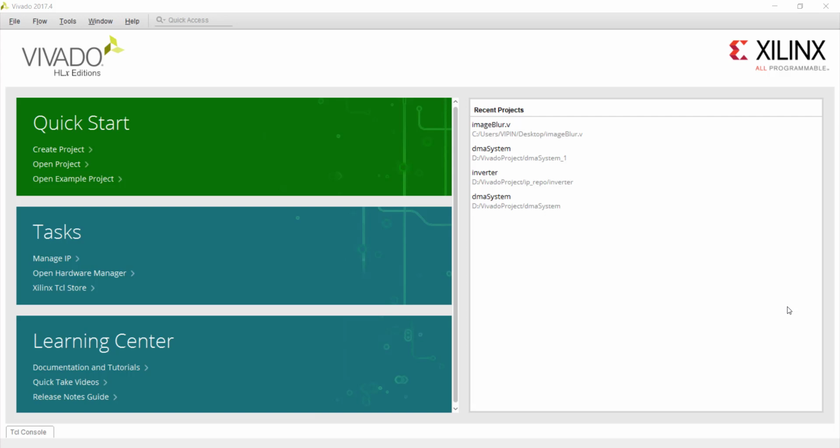That is one reason. Sometimes you want to use Xilinx IP cores because they are more optimized. Even if you write the equivalent Verilog or VHDL code, if you directly use the IP cores from Xilinx, most probably they will give better performance in terms of clock as well as resource utilization, because these codes are written by Xilinx engineers, so they are more optimized.